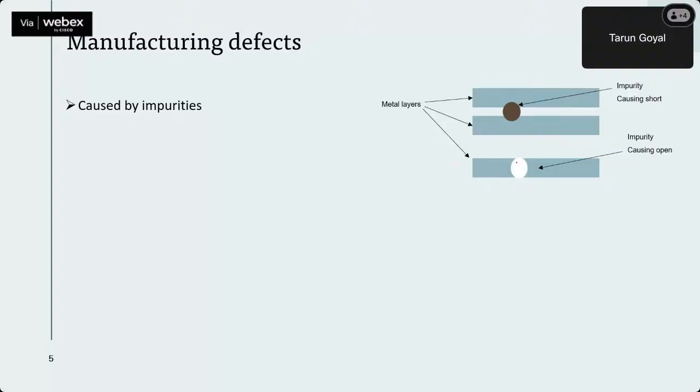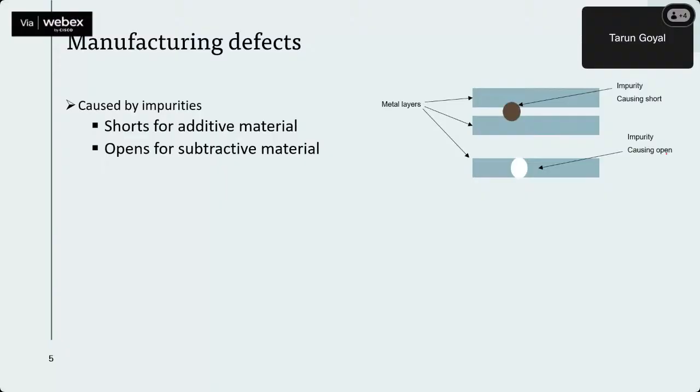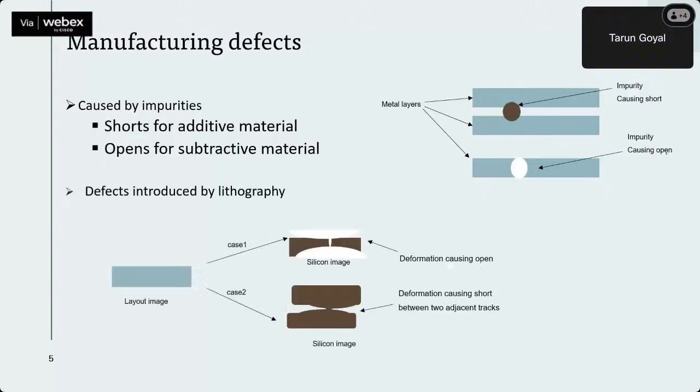So that's one kind of defect during manufacturing. If a metal line was created and it has an impurity in between, creating a void, an open, then that impurity causes an open. These are the two very basic defects we call shorts and opens. Another one: suppose this was a transistor and this was a layer with a very thin, narrow connection, and the remainder is broken here. All these deformations are defects, an extra thin layer between two metal layers, which also causes shorts.